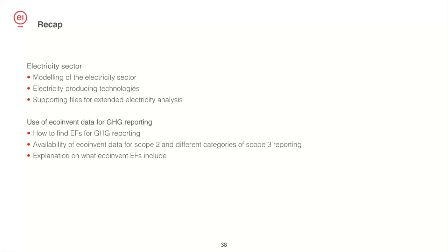So I think creating a new electricity mix is pretty straightforward, depending on how you use it. If you're just looking at ecoinvent or just using ecoinvent through ecoQuery, for example, you can also collect the electricity producing activities individually and then build your own market by also adding emissions and transformation and transmission losses.